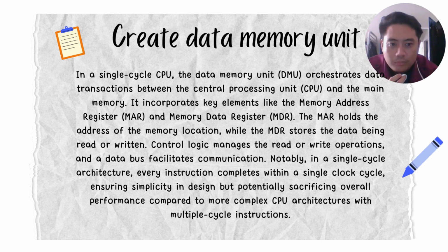In a single cycle architecture, every instruction completes within a single clock cycle, ensuring simplicity in design but potentially sacrificing overall performance compared to more complex CPU architectures with multi-cycle instructions. So we were given the task to create the data memories for the single cycle CPU.